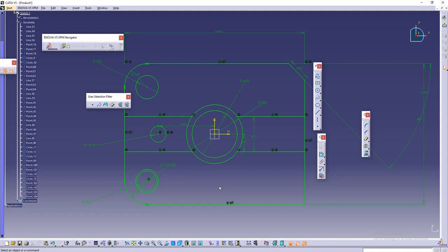So it is 500 from here. And then if I want to mirror it, I do not have to create any plane or section, because in CATIA everything plays around the center and the center plane. You have to put constraints along the axis, and all the part references and dimensions you need to put along the axis.